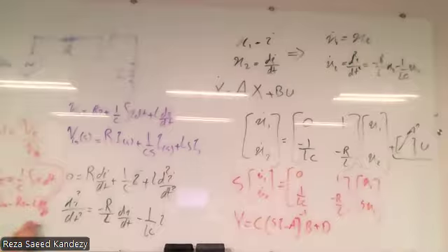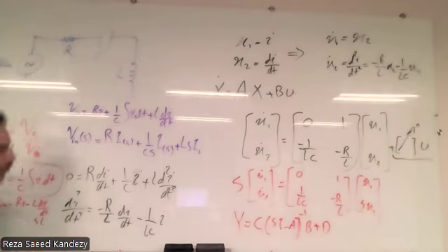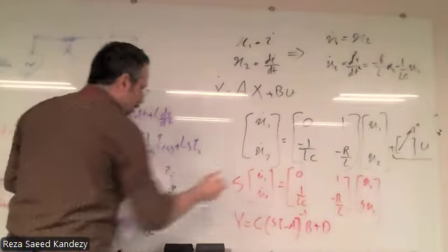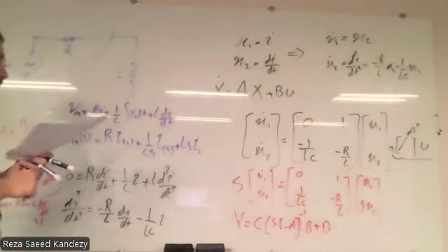So you can take a Laplace transform of this, and you can develop the transfer function, that D matrix. This is LS, okay? This is going to be Ri, this is going to be V in in the S domain, and you have your Y for your transfer function.